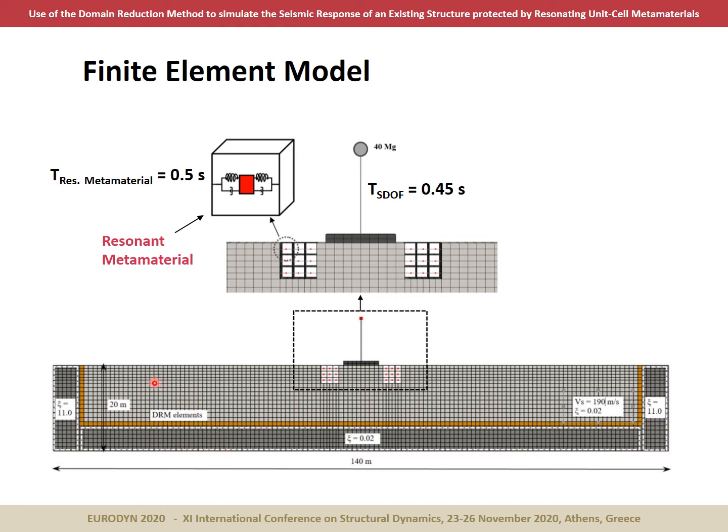domain. Notice here, however, that this is not how the domain reduction method should be used in general, since those outer elements should always have high damping to damp out the radiated waves. But in this particular case, let's say we have implemented an ad hoc solution that works for our case, but we don't recommend it for new users to try something like that.